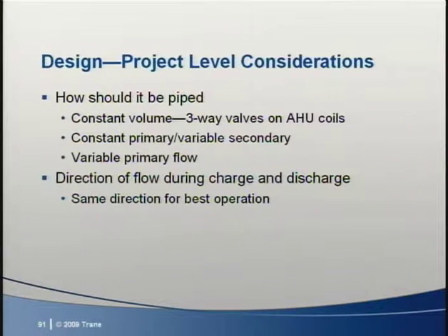But whatever architecture you select, the direction of flow during charge and discharge should be the same. That can be tricky in some designs, especially parallel designs. Because of the way the ice melts on the surface of the tubes, it's better to charge and discharge the tanks in the same direction.